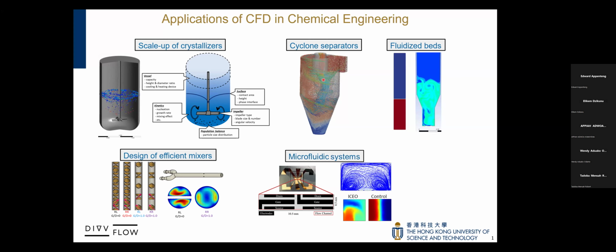It's the same for the case with this third tank, for instance, where we have those particles. Each individual particle is being tracked. So that is the difference between an Eulerian approach versus an Eulerian-Lagrangian approach.